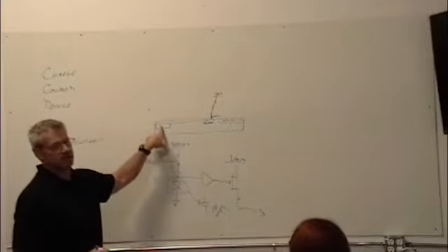What you would do is you would have three sensors, kind of like this, and you have a prism in front of them. This would be a low-pass red, and this would be a low-pass green, and then everything else would go through. And then you'd have an infrared shield on this end to knock out the infrared. So now you've got red, green, and blue. And that's how you break them up. Or if you just had the one, then it was black and white. Or they play a game with a color wheel that would spin in front of it.